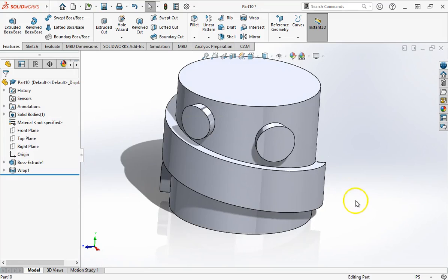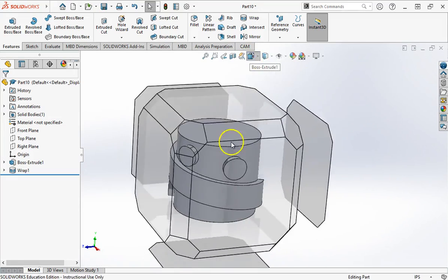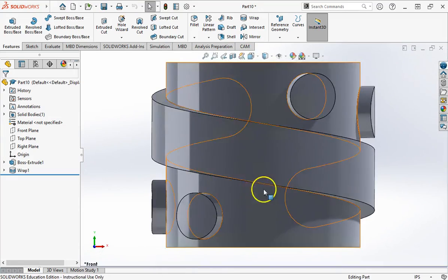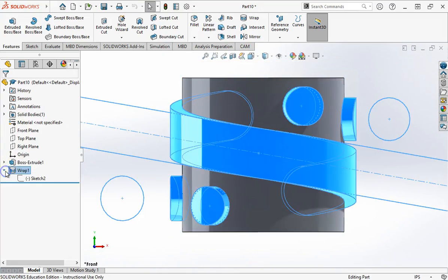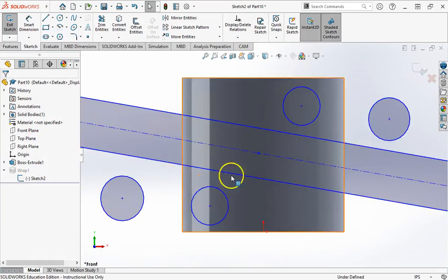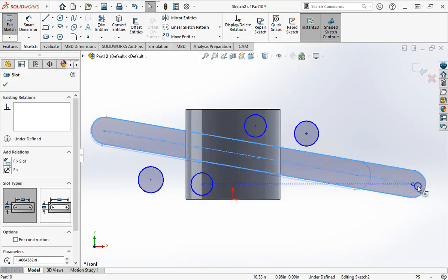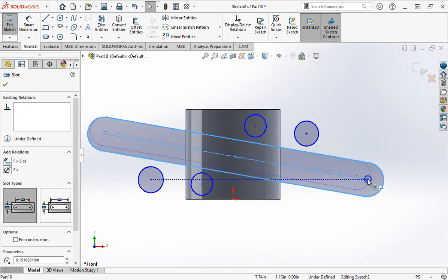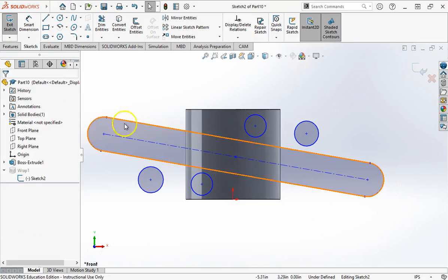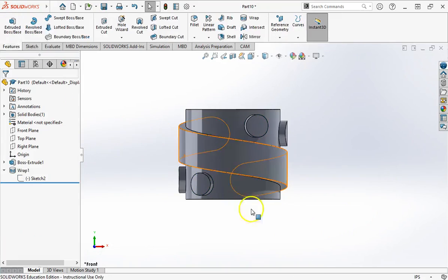I think there are a few things to be careful about whenever you're doing this. Generally, whenever you're doing your sketch, follow the sketch rules. Make sure you're not intersecting your shapes. If your wrap starts to overlap itself, say if I extend this way out far, it might wrap around and collide with itself, which could be something that you want to do. Maybe it's not, but it all depends.